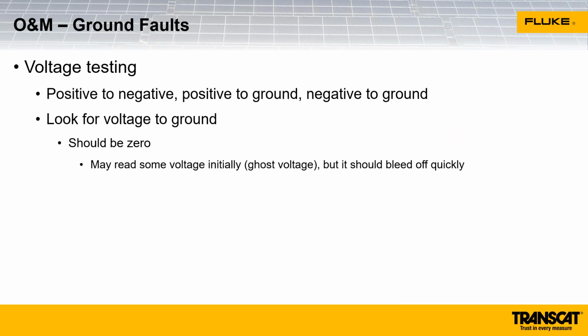All right, moving on to talking about ground faults. This is one of the most common issues we see in operations and maintenance. There's a way to do voltage testing on our strings of modules to identify where the ground fault is located within a string of modules.